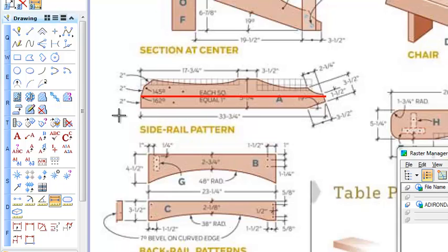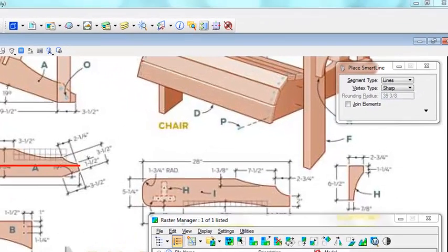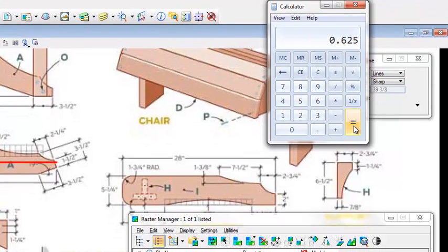So what I need is a ratio to scale this up to make that line equal 33 3/4. What would happen if I type in 33 space 3/4 divided by 2 space 5/16? 14 5/8. It should be our multiplier. And 5. So we'll just leave that there. Go to our calculator real quickly. Say 5 divided by 8 equals, so it's going to be 14.625.